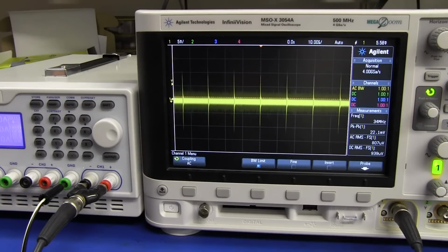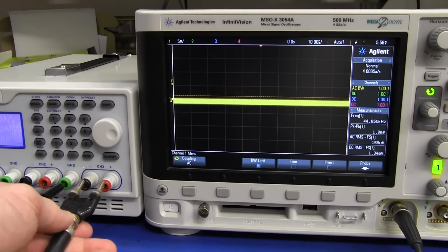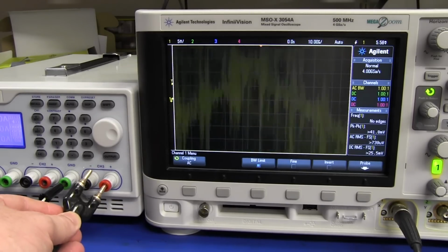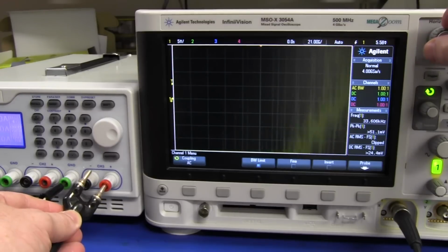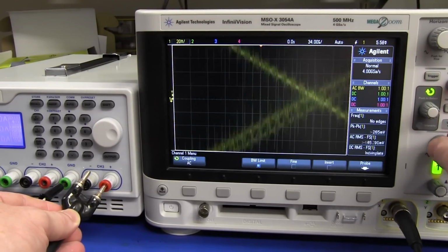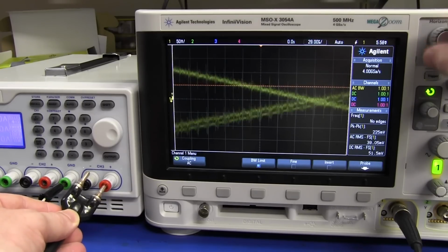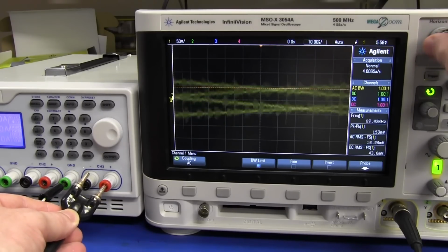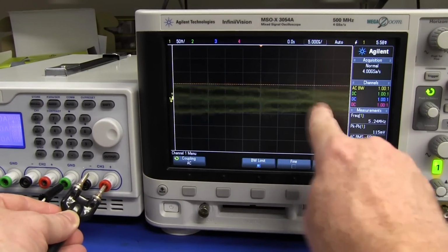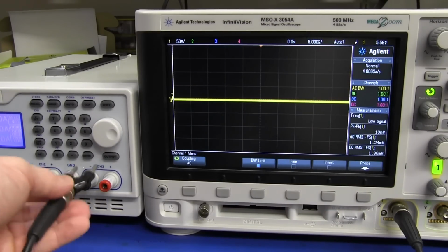Now, the first thing we might check is what happens when you disconnect it. Okay, you disconnect it, it goes away. Not a problem. Let's connect one side of it. Not a problem. Connect the other side. Well, we're just getting 50 hertz garbage on there, right? So let's not worry about that too much. But look, you can see the switching component, folks, is still... Oh, I accidentally hit it. The switching component is still in there. There it is. You can see it. So it's definitely coming through this power supply.